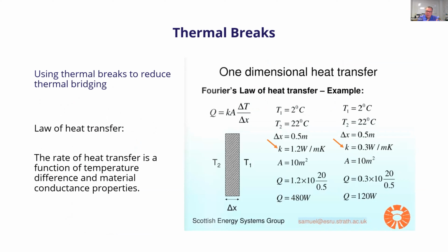This particular slide, yes, it's in metric units, but I like it because it's an important takeaway when you're thinking about using thermal breaks. And that is that the thermal conductivity of a material is a function of area, temperature difference, but also the conductance of the material, okay? And that is a function of thickness. And so all of these variables work together to control the heat flow coming through that material.